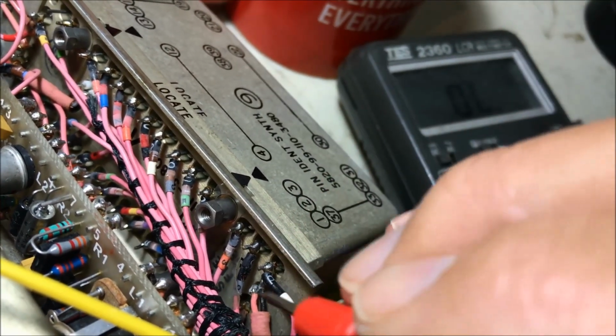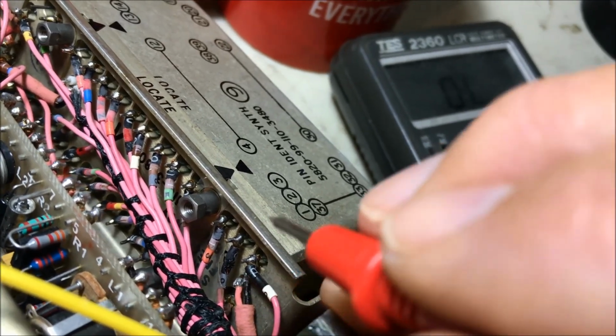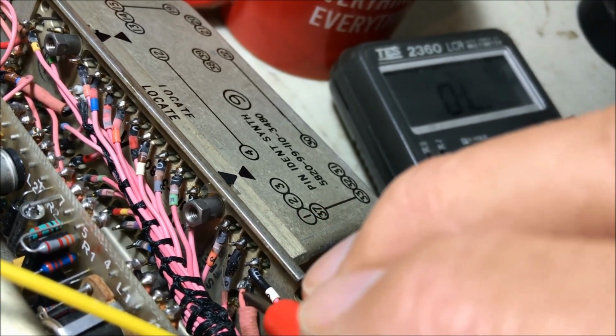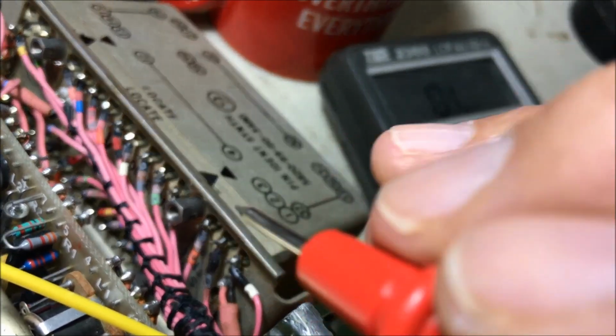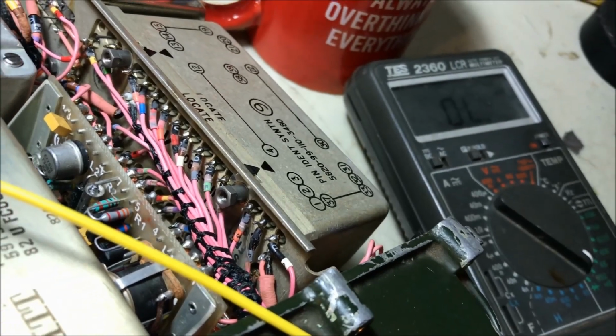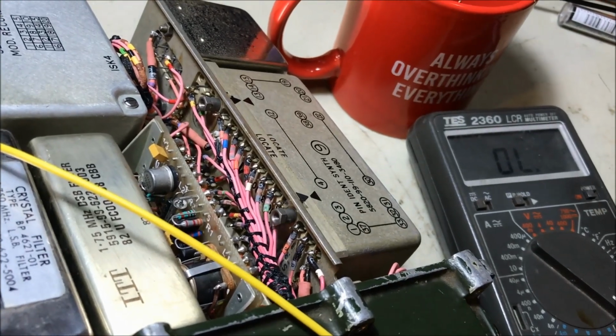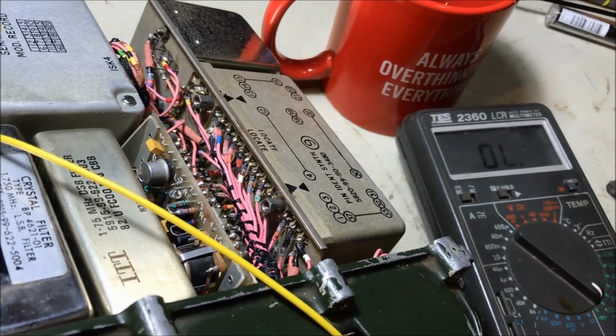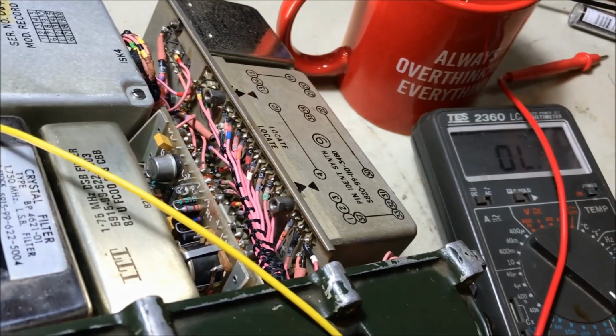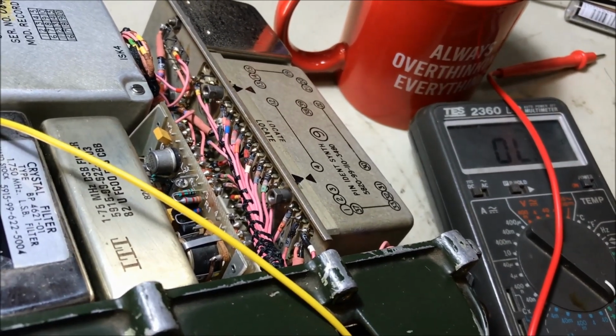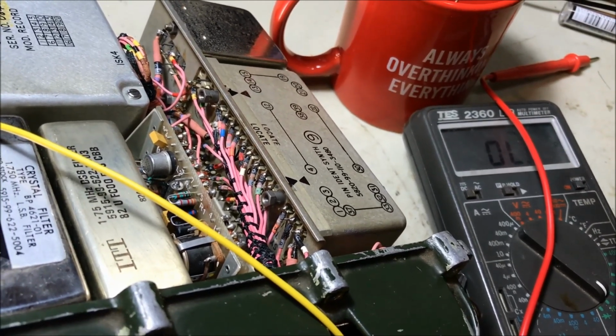So we're going to unsolder that. We're going to solder a little flying lead, bring it up here. We're going to solder another little flying lead to the cable and bring it up there. And we'll be able to connect them together with the synthesizer back in position. So we can run the radio and have the pleasure of being able to disconnect that, reconnect it, and put an external DC supply onto the tuning section. So there we go.